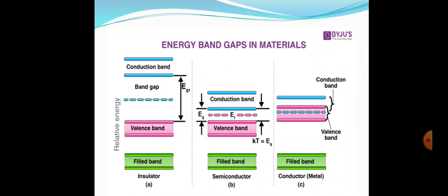The conductor, semiconductor and insulator can be explained with the help of energy band diagrams. In the first case, for conductor, the valency band and conduction band overlap with each other. You might know very well that the outermost electrons are called valence electrons. These electrons together form a band called valency band. The empty band over the valency band is called conduction band.